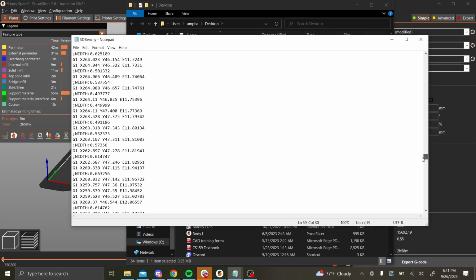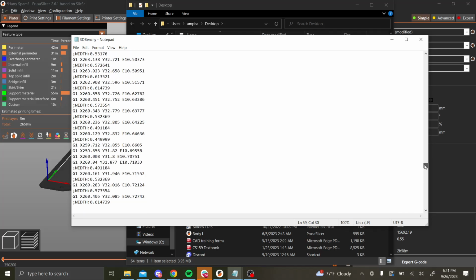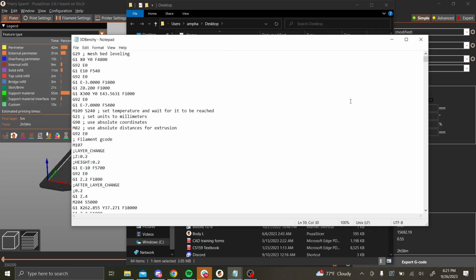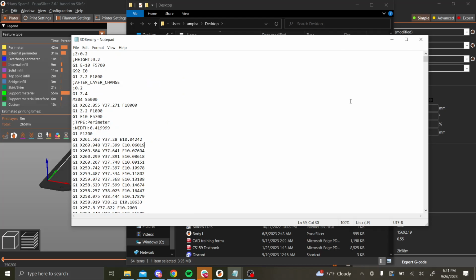And each movement is very small and precise, if that makes sense. Each line tells it to move a little bit. How long is each step? Well, it depends on the movement command. Between these points it's maybe half a millimeter in one direction, and fractions of millimeters on this end. And E is for extruder, so it's how much plastic you want to push. So yes, it's very precise.